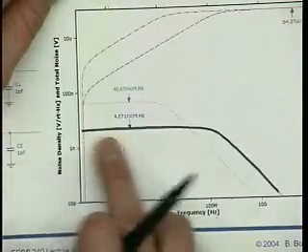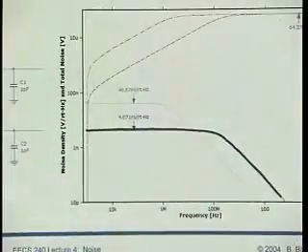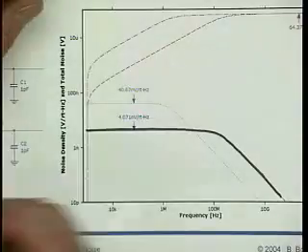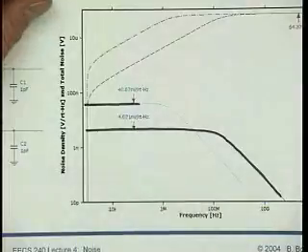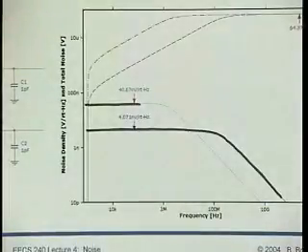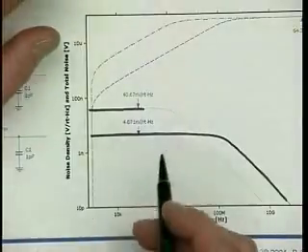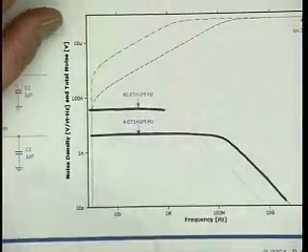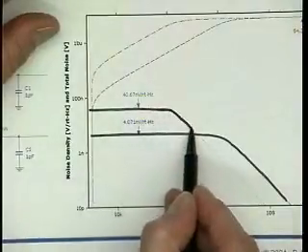I have 4 nanovolts at low frequencies, but then the noise stretches out to fairly high frequency because I have a low resistor, a fast time constant, a high frequency pole. The higher valued resistor produces a lot more noise, 10 times more noise voltage at low frequency. But because it's a higher resistor, it starts rolling off sooner.